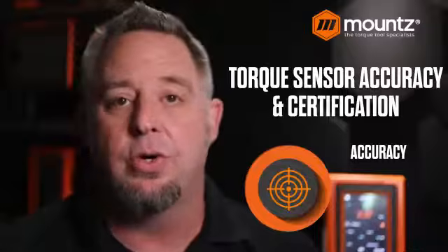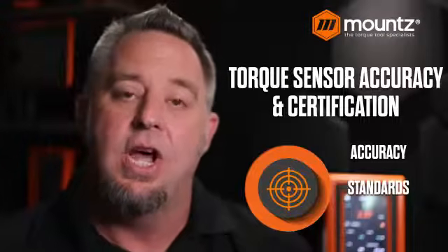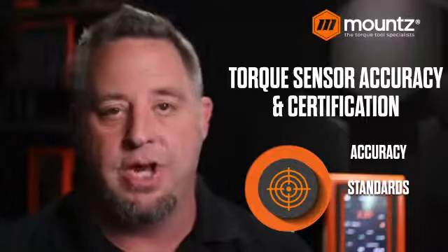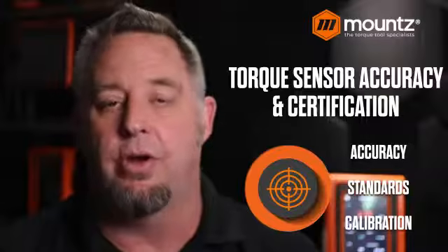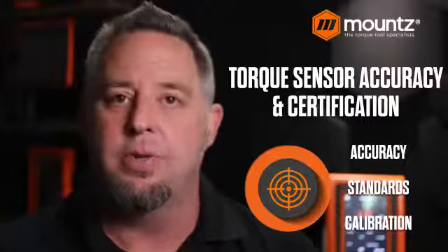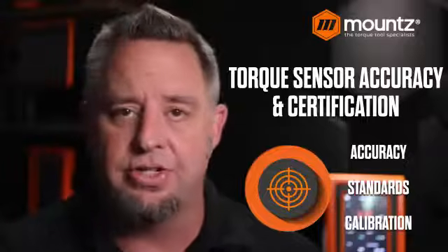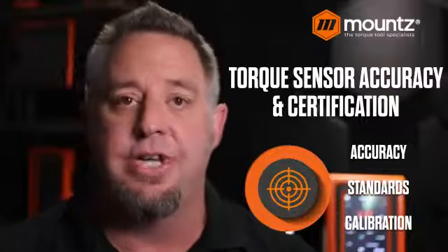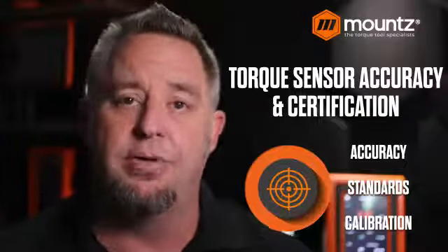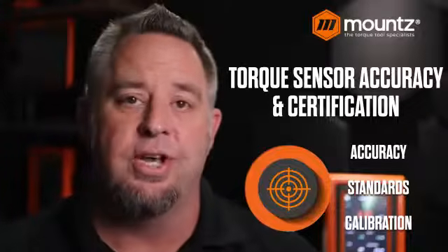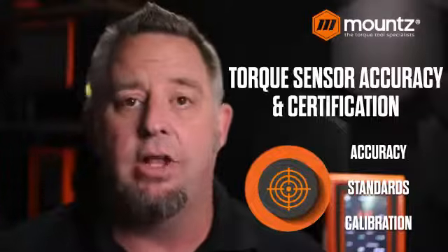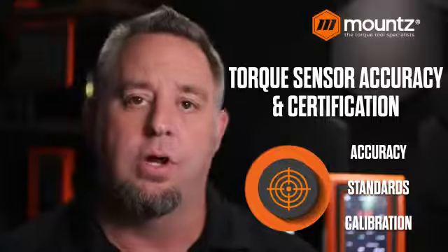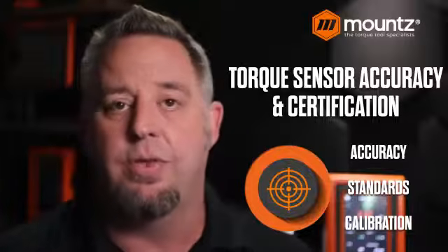So just like any other torque sensor, it does have an accuracy. If we couple that sensor with a torque analyzer, then we can use what would be the paired or system accuracy. And that's typically for the Mountz analyzer with a sensor. We have a system accuracy of plus or minus 0.5% from 20 to 100% of reading of the full scale of the unit. And that's typical for all of our sensors that we have within our line.